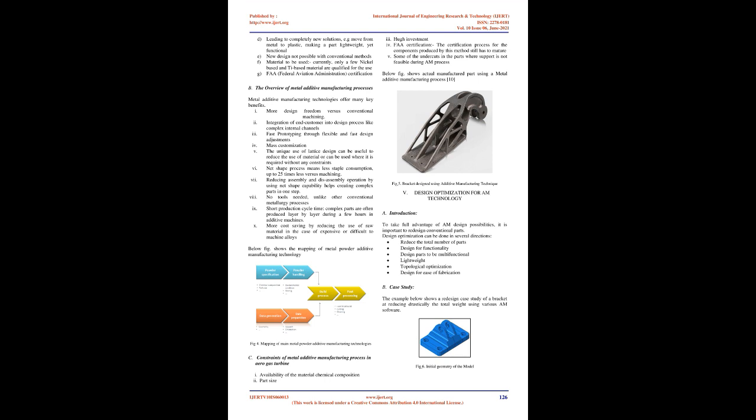Below steps are involved during the selection of aero engine parts which are suitable for a metal additive manufacturing process. A. Size of the component. Currently, this technology is explored up to only a part size of 450 mm all around and a height of 1500 mm. B. Enabling a completely new design approach. C. Resolving the constraints of conventional manufacturing.